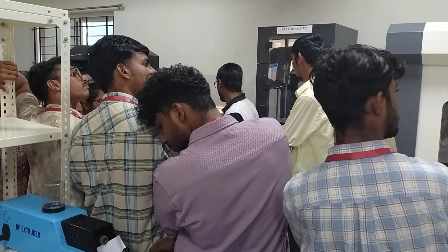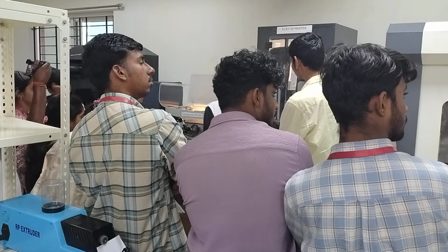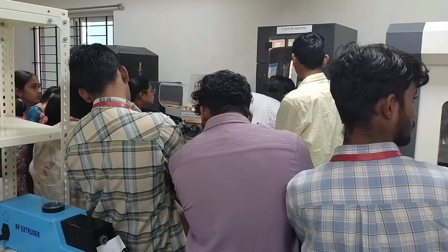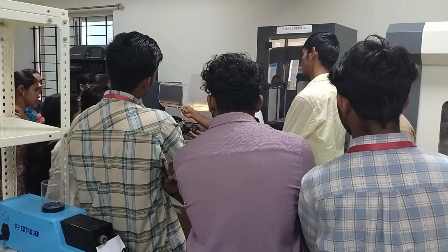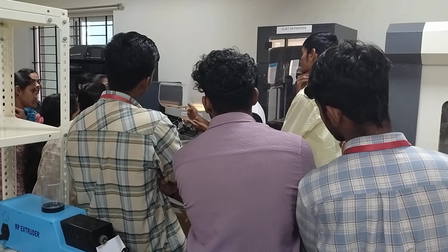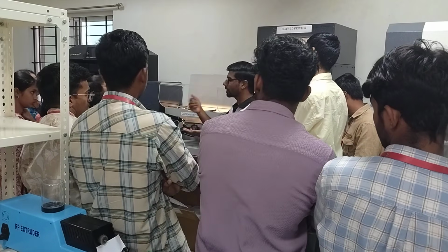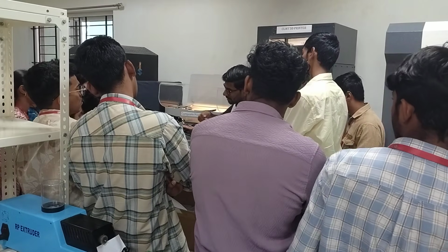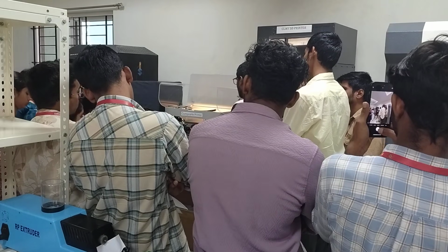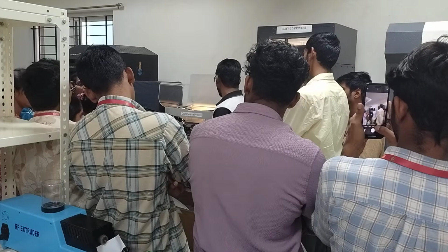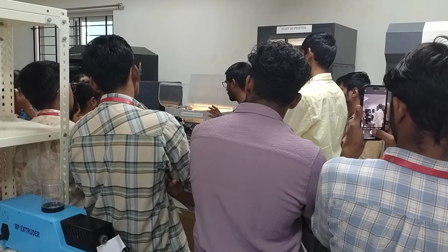So it is running a purge line. This is one thing that you want to see, that purge is happening. Yesterday I had printed some parts. Purging is when some of the filament is stuck here, or the filament is not reaching up to the nozzle, and if we start printing, it may start printing the air and the print may not come out properly. So extra material is deposited on the bed to make sure that the temperature is proper and deposition is good enough. That's why it deposits some extra layer before printing.